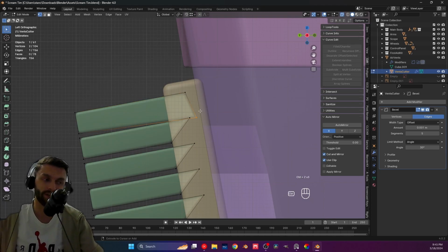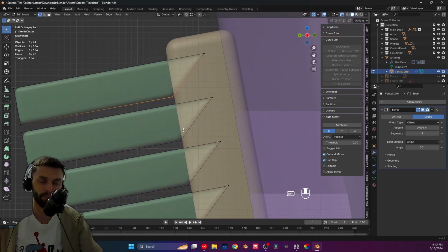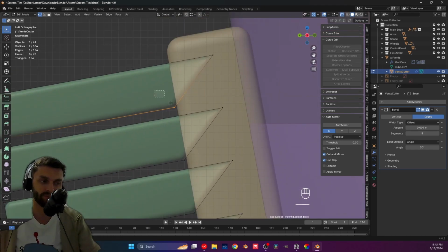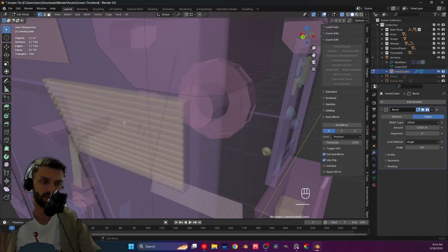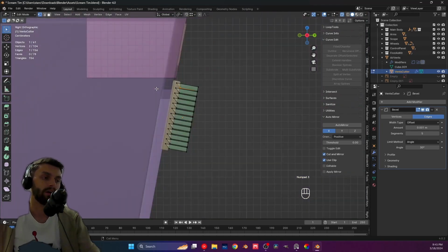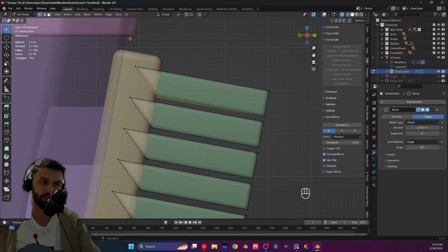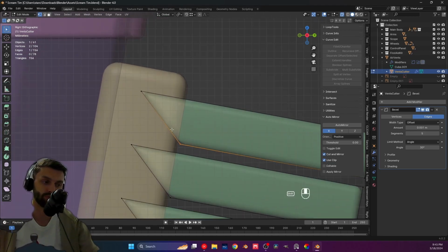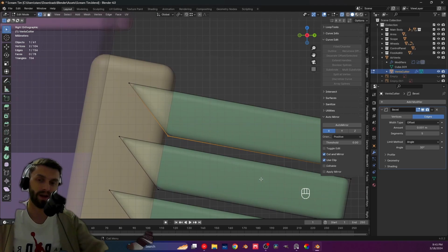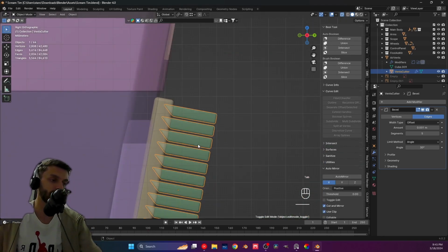And that's why you do it the reverse way, to basically cut through and make the cut like this. A very important aspect is to have these second vertices right here, because there are two of them, on both sides, so don't forget that. You have to have them a little bit out of your original cube from which you cut, so it's actually cutting all the way through. So just make sure you have that, right? And once you have that,